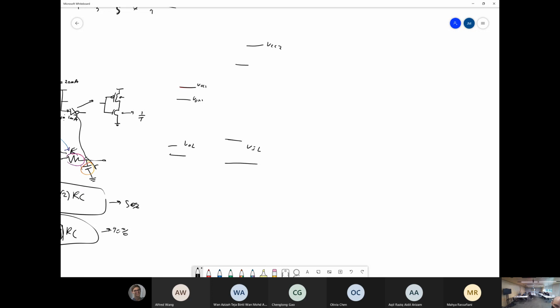And V input high. Now, if we have a 0 on the output here, we flow into where there's V input low. We're happy days. If we have a V output high here, well, if this is our forbidden region for this logic gate, and this is our forbidden region for this logic gate, we're in our forbidden region, right? It won't work. So we need to shift this level up to here.